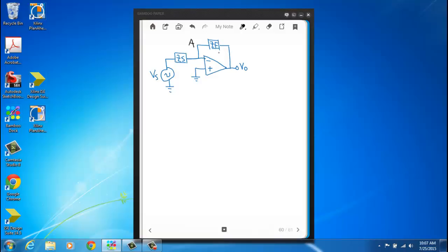Well, when we represent the low-pass filter like this with impedances, remembering from your circuit theory that we treat impedances just like resistances, and that impedance has units of ohms just like resistance does, it should make sense that V out over the input Vs for this circuit is just minus the impedance in the feedback divided by the impedance at the input. So the only difference is we have impedance instead of resistance. Really, we're just treating the low-pass filter as an inverting amplifier with impedances instead of resistances.